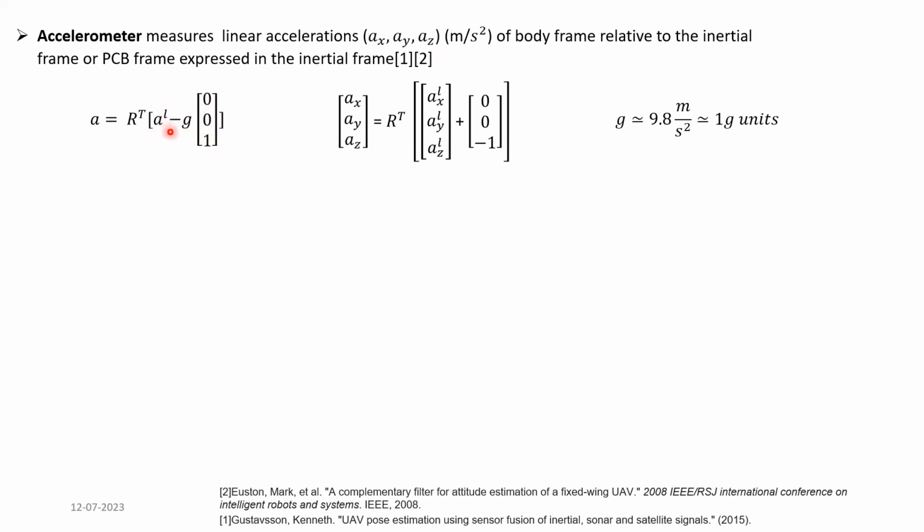So I'm just separating these terms, and I'm assuming this linear acceleration AL is very small because the acceleration for an orientation body is very small. AL is the acceleration you are receiving from the accelerometer, right? Yes, both are from the accelerometer only. I'm just dividing the normal accelerometer acceleration values along with the acceleration due to gravity. It will also pick up the acceleration due to gravity.